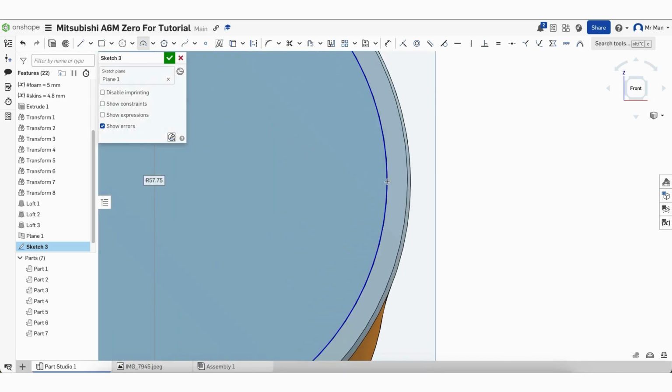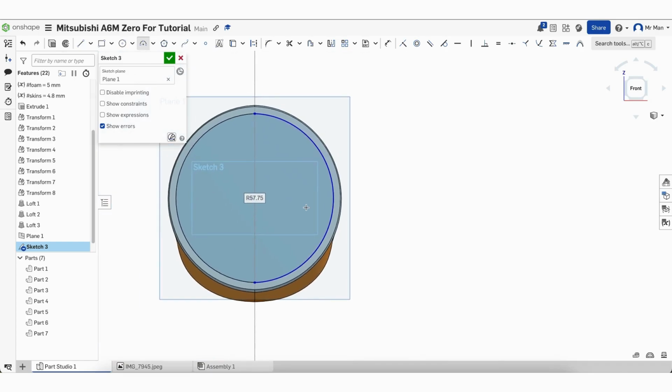So now we select mirror. Or no, it's not mirror, it's offset. Select offset. Select the line we just drew and move it in. So now we're basically making a new smaller line, or curve in this instance. Change that to 8. Perfect. Now we can just delete this line. Okay, now we go to mirror. Select the middle plane line. Then that. There we go. We have the lofting sketch.